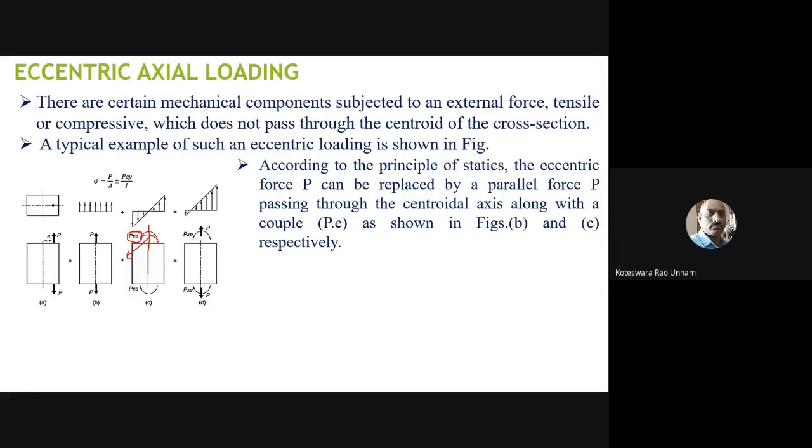So here, because of this bending moment, the bending moment is something like this. If I apply it to that cross section, it is something in this direction. It is like this and like this. Because of this kind of bending moment, the top layer is subjected to tension and the bottom layer is subjected to compression. Therefore, you have a tensile stress here and a compressive stress there. At the neutral layer, or at the centroid, you have zero stress. So I can plot the stress something like this.